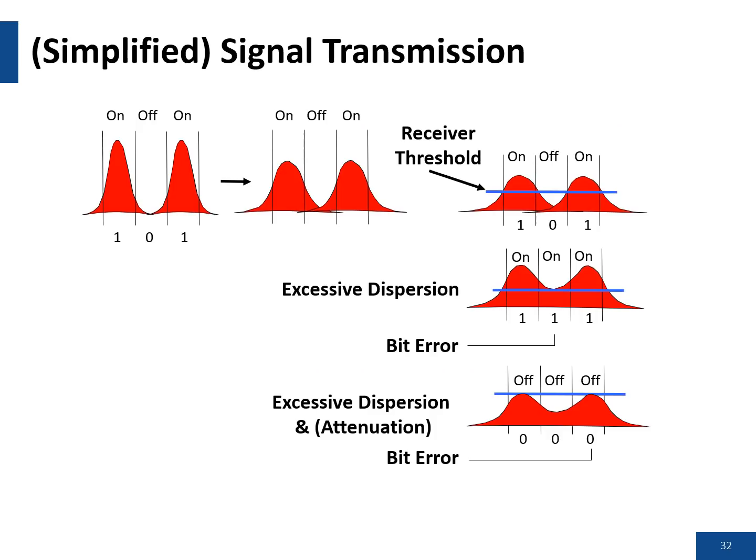Binary code, you're seeing an example of binary code where you have pulses of light. There is a threshold for the receiver, and any energy above that threshold is considered a 1. There's also a duty cycle, or a period of time based upon the bit rate or the available bandwidth.